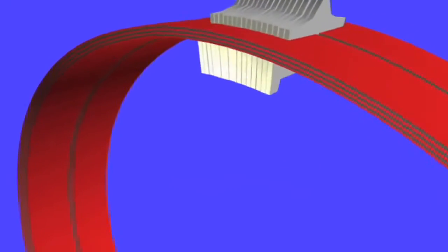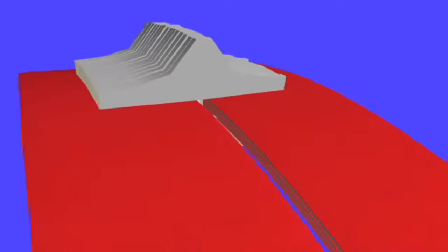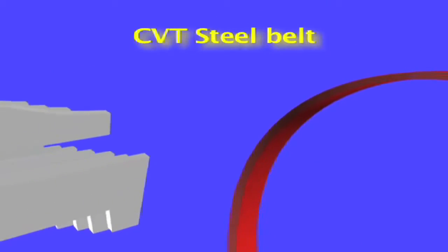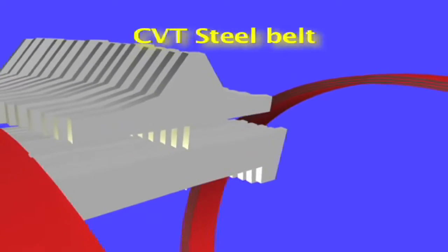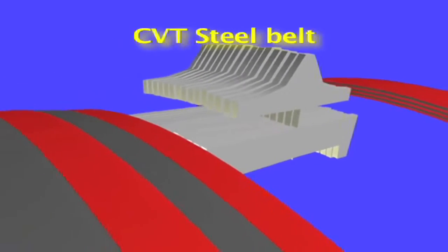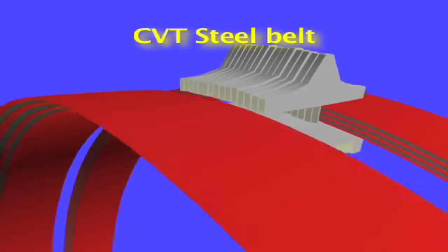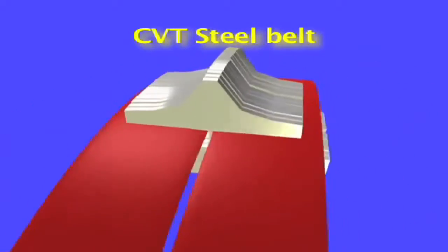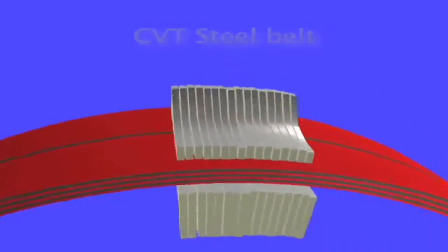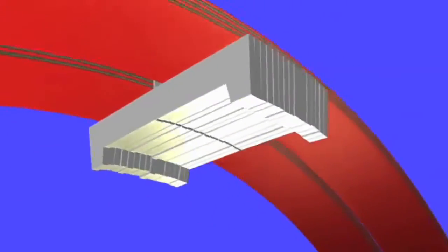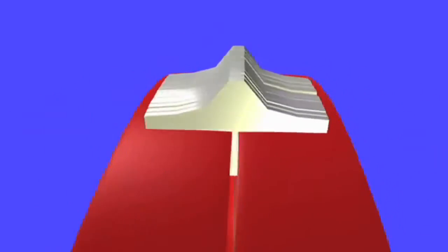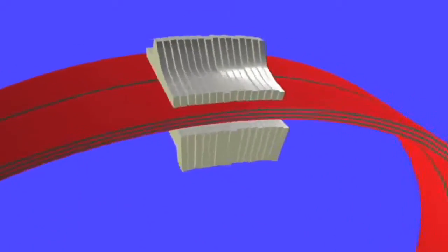The CVT belt consists of 2 ring packages of 6 or 12 rings each, and approximately 400 to 800 elements, 2.5 inch width. It has been this component which has prevented the technological development of the CVT in the past, which was made of rubber exhibiting poor quality. The modern CVT belt works more by shear force rather than tractive force.